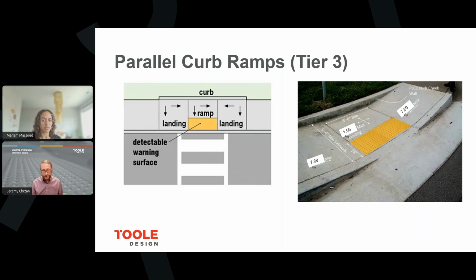So not only is a pedestrian who's trying to cross here during a storm having to cross a wider area of flow than they otherwise would have at a perpendicular style ramp, but it often means that there's also then debris even after the storm has passed. And so while it's always good practice to install an inlet upstream of a curb ramp so that a pedestrian crossing any curb ramp doesn't have to ford a stream to proceed along their crossing, for this style curb ramp, it's even more important to address that collection of sediment and spread of flow that tends to happen.